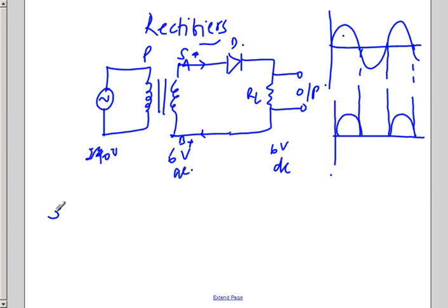So here, if you see, minus is connected to P type and positive is connected to N type. It means the diode is in a non-conducting state, or it is in reverse bias. In reverse bias, though we say a very small amount of current is flowing because of the minority charge carriers, that can be neglected.